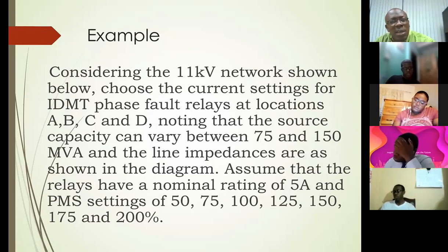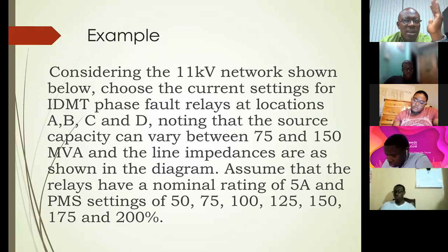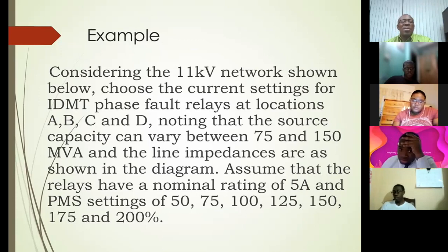We are giving it here on the secondary, but of course, if it's nominal 5 amperes on the secondary and you have a 100 to 5, then the nominal on the primary would be 100. Is that clear? So the nominal we are giving here is a nominal on the secondary of the CT. But in your case, you'd agree that if I am dividing 5 million by 30,000, and I divide both the 5 million and the 30,000 by 20, I'm going to get the same answer.